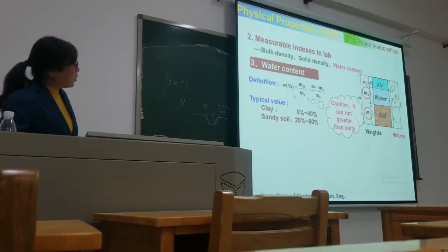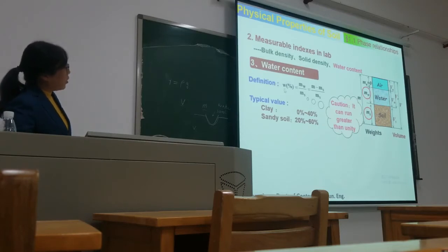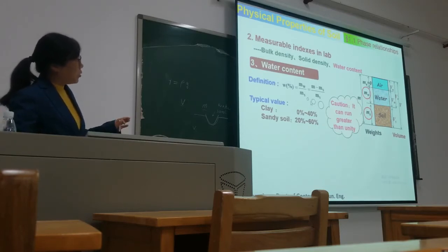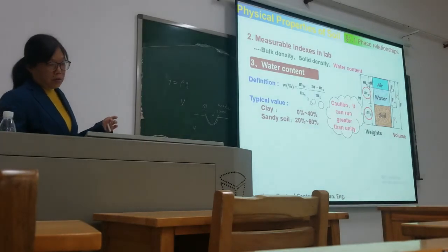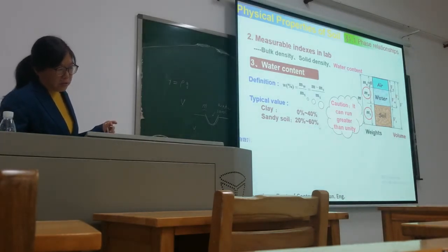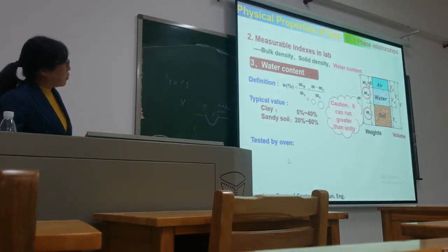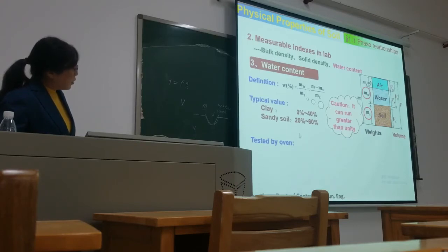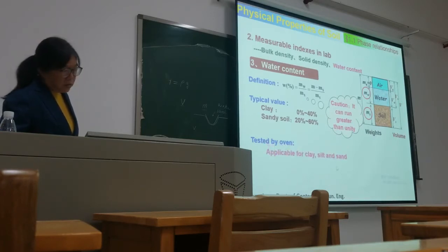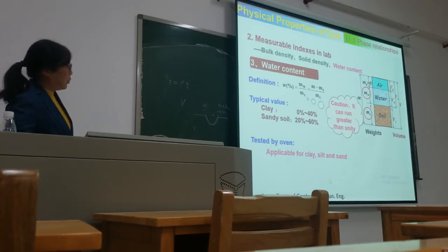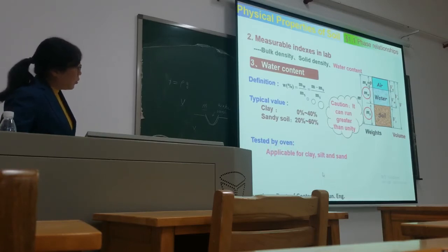Here, the water content may be more than that. The suitable method is oven drying. This method is applicable for clay, soil, and sand.